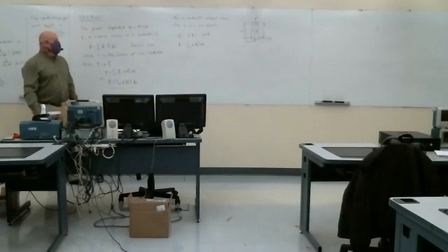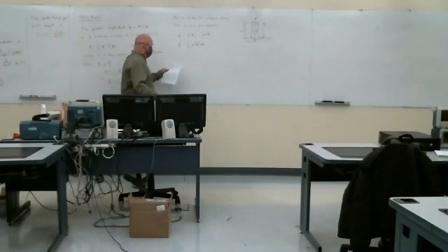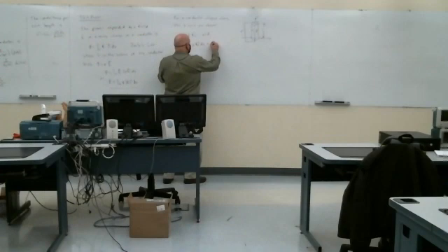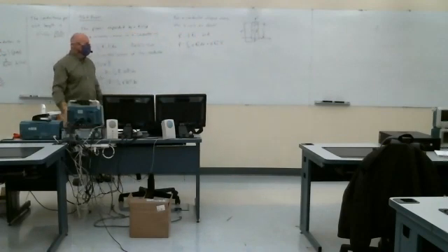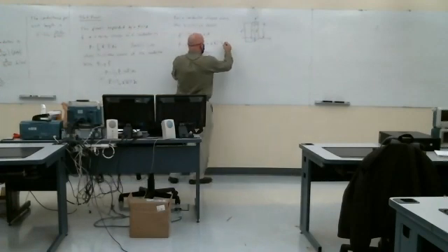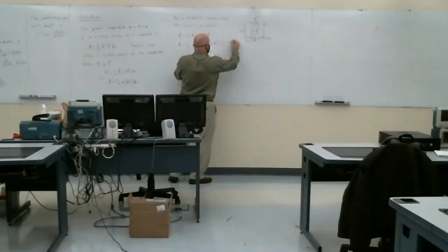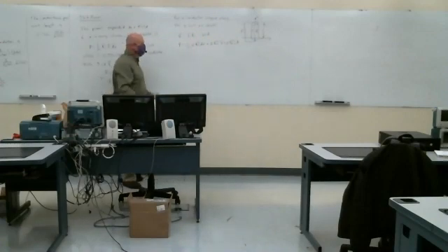So EZ squared times sigma, integrating over the volume. But sigma and EZ are constant throughout the volume, so that becomes sigma times EZ squared times V, where the volume of the cylinder is its length times its cross-sectional area, L times A.